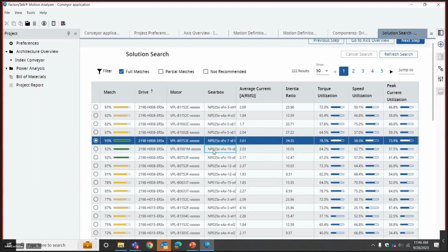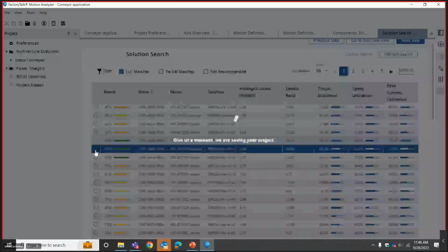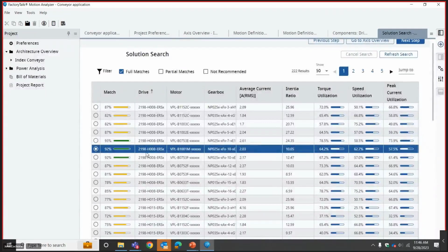The other thing you've got to keep in mind is the gearbox pricing, and the cost for gearboxes. They can vary widely. But typically we'll look at a single-stage gearbox up to a 10-to-1 ratio. And beyond that, we've got to go to a two-stage gearbox. So I try to take advantage of a single stage as much as I can and stick with the single stage, because my highest reduction for a single-stage box is the 10-to-1.